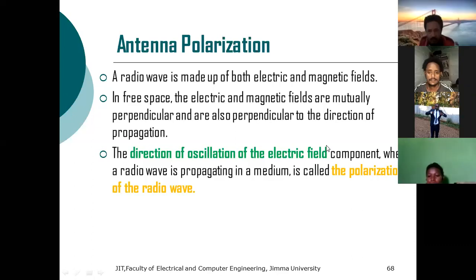If the electric fields are oriented in perpendicular directions, for example, if we assume a spherical coordinate system and one polarization is along the phi and the other polarization is along the theta direction, if the magnitudes of these electric fields, which are perpendicular to each other, are different, normally it shows an elliptical phenomenon.